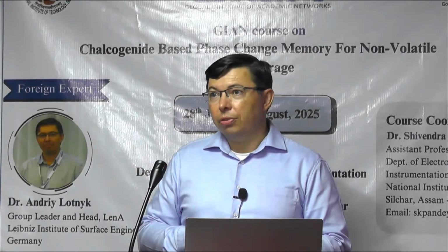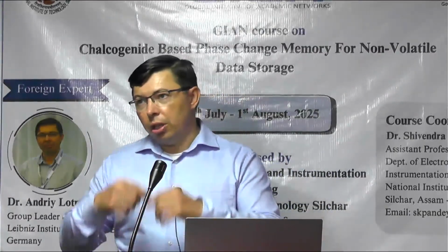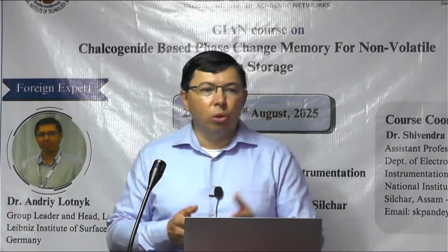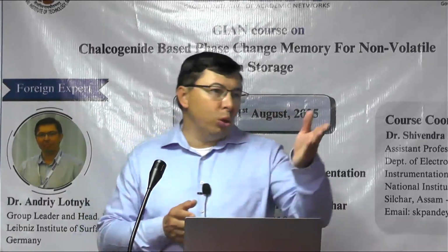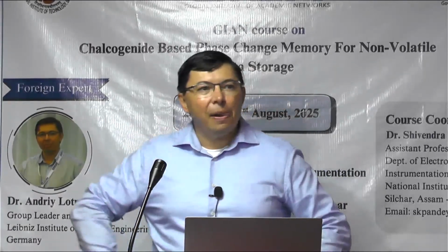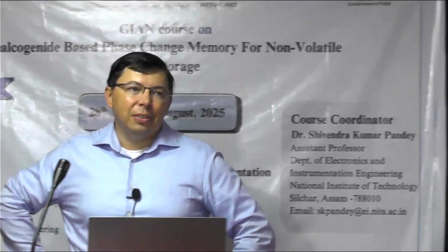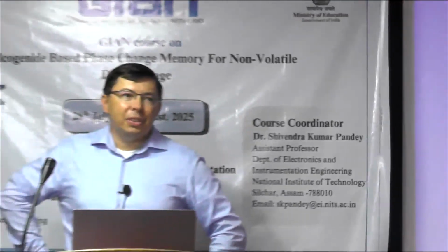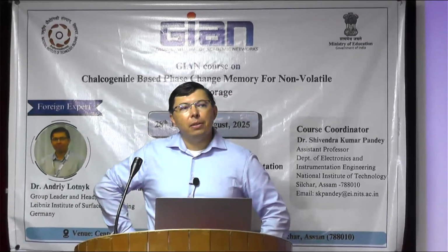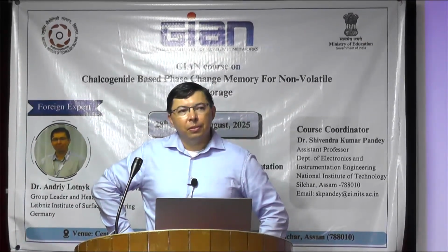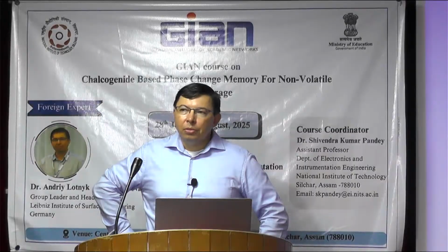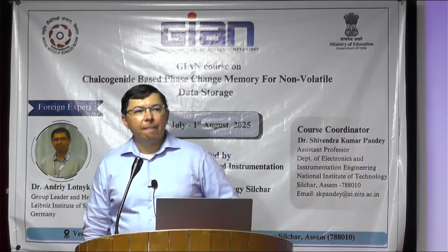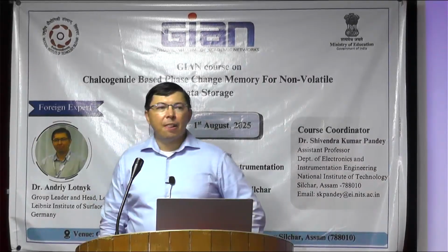Of course, yes. If you just expose it to air, this oxide forms very quickly. It was confirmed by many groups, and also by you. The thing is pointing out clearly the way when you are depositing. So after deposition you just cap the material in the same vacuum. The desiccator way which you are telling, it will definitely affect.